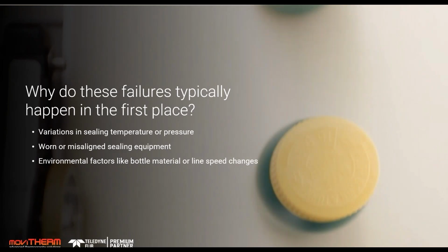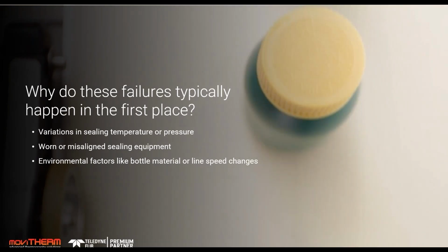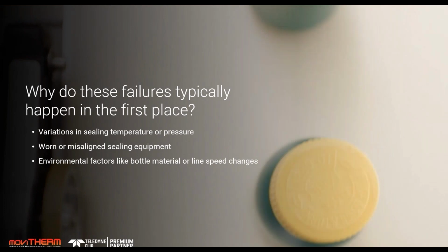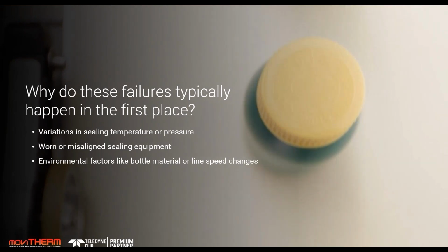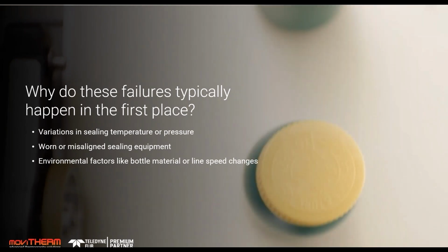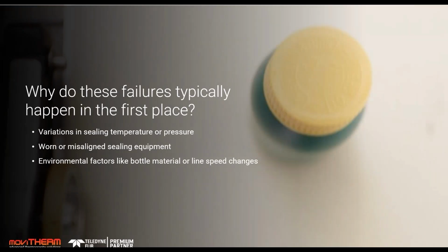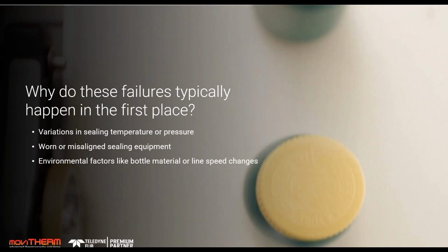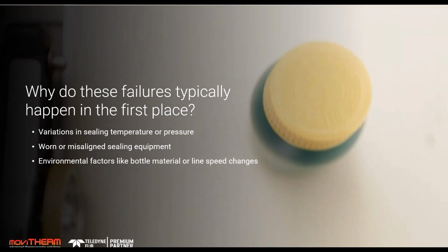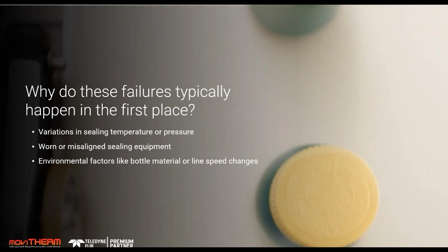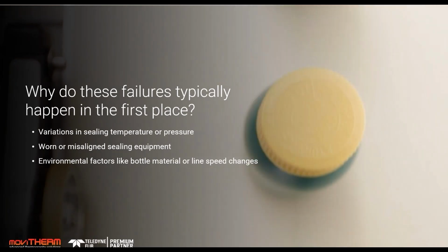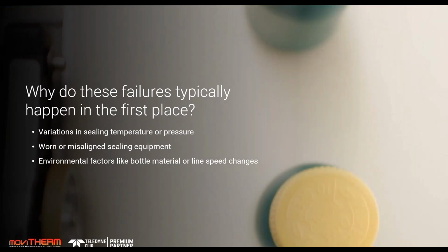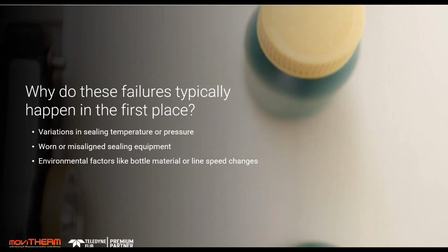Yeah, well, we've seen a lot with, I would say some of the biggest ones were with torquers. I would say that's a big problem. When you're getting issues with torquing, it's gonna show up on the thermal signature. Remember, when we're looking at this, there's really three factors. There's time, pressure, and temperature are the three factors that are creating the seal.